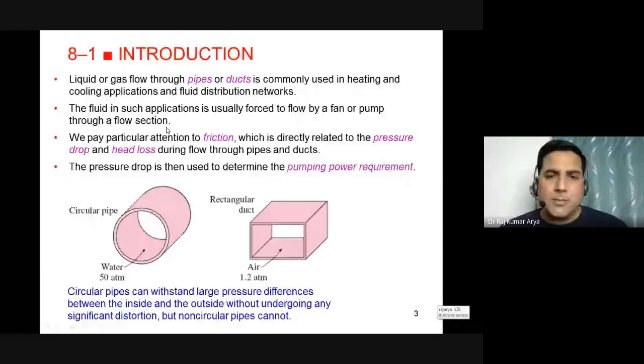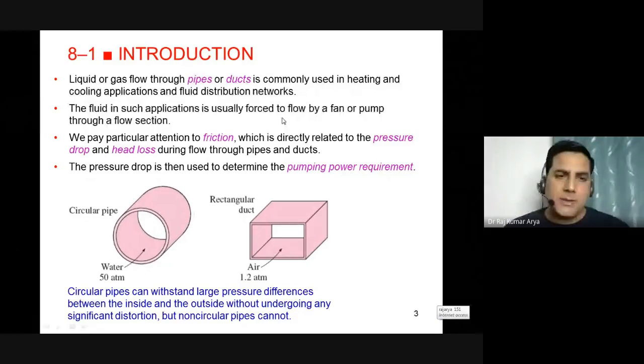In that case you have only one-time pumping cost, and throughout the day you are draining the water. But your pressure head is fixed. You cannot change it. Whatever the height of that particular tank, that much is the pressure you can avail at the exit. Now, what will happen in case of pipes? You have so many connections, and the pipe would be rough from the inside.